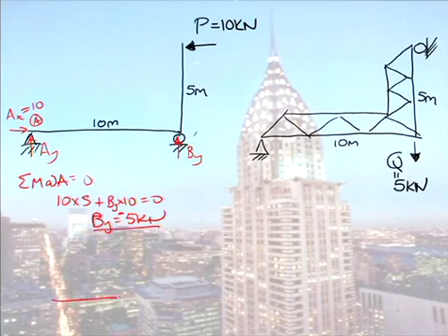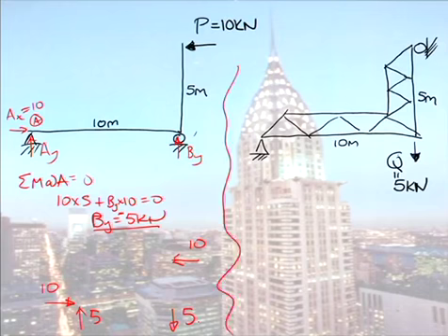So if I now draw my system here of forces only, leaving the structure out, I have a force here of 10. I have a reaction here of 5 down. So what's AY equal to? 5 up. And I have a horizontal reaction here of 10. And you can see by looking at that, you can see X and Y equilibrium quite easily. If you do take moments, you could see moment equilibrium.